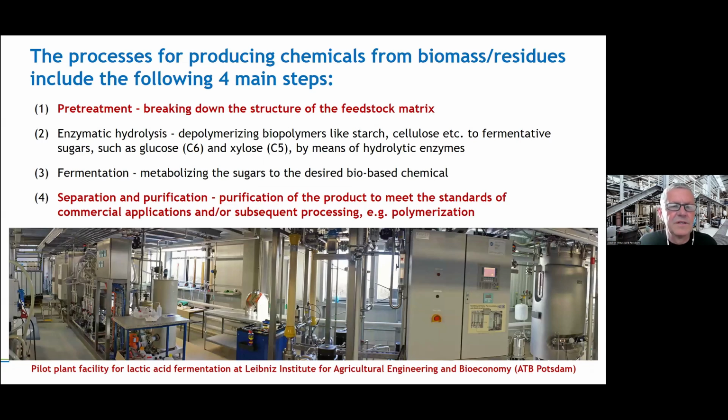You all know the four main steps of those bioprocesses, and here again a nice picture of our pilot plant, which we put into operation in 2006. It means next year we are celebrating 20 years, anniversary. And this was really very important in what I was mentioning already, the scaling up of processes. And you see on the right-hand side of that picture our biggest fermenter, 450 liter, connected with all the pumps and equipment like the hollow fiber membranes to run it also in a continuous mode.